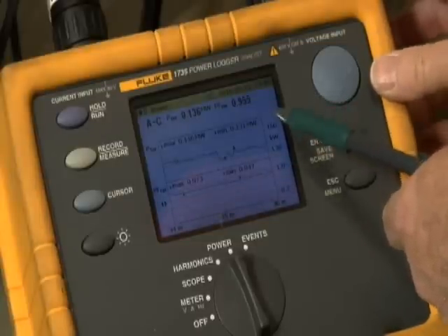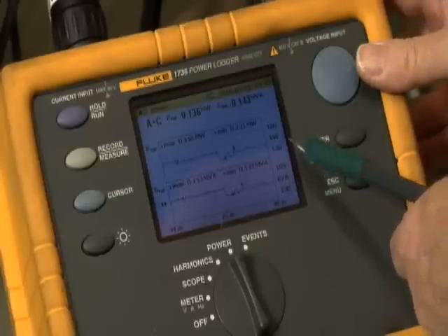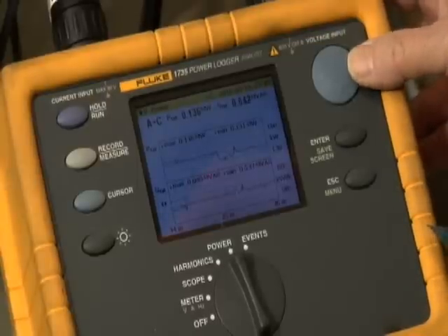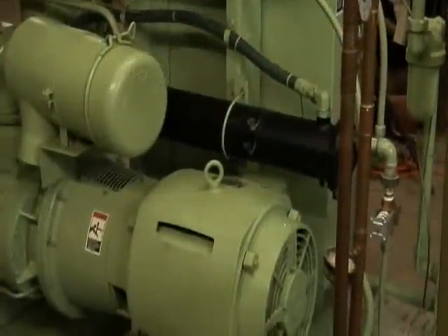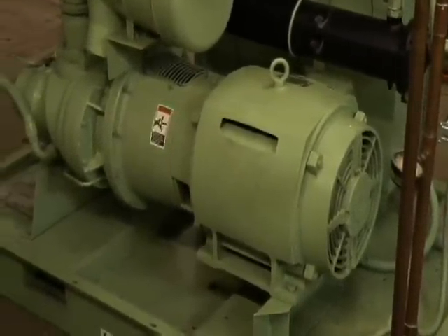I recommend taking a look because it's worth checking if your kW draw is high as compared to the utility. If you find that your kWs are high, compare the log data to your operating schedule. Is there a correlation to a particular load activity? If yes, you know where to hook up your logger next. Keep moving your logger downstream to large loads and find out how much energy they are consuming.